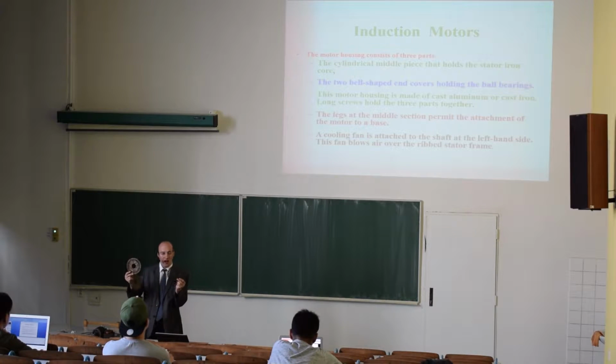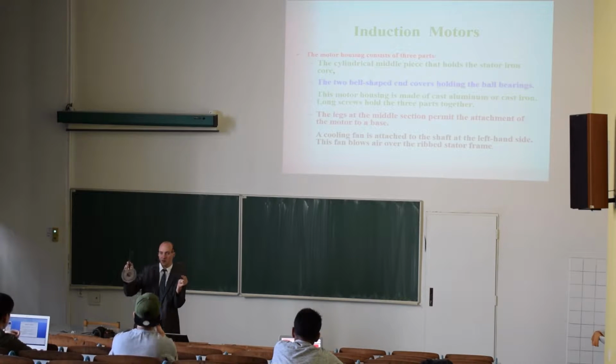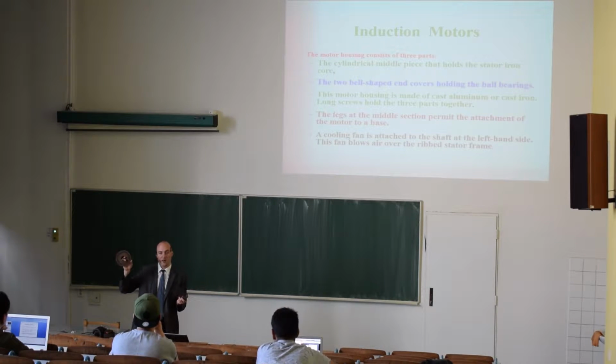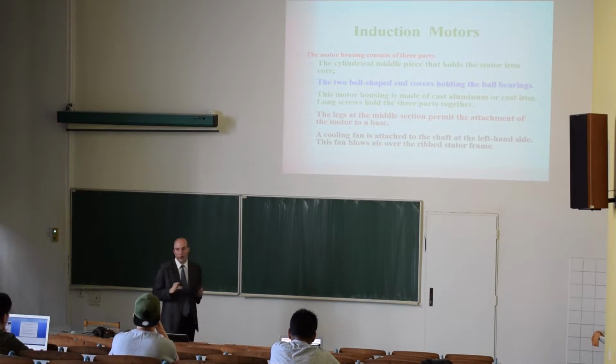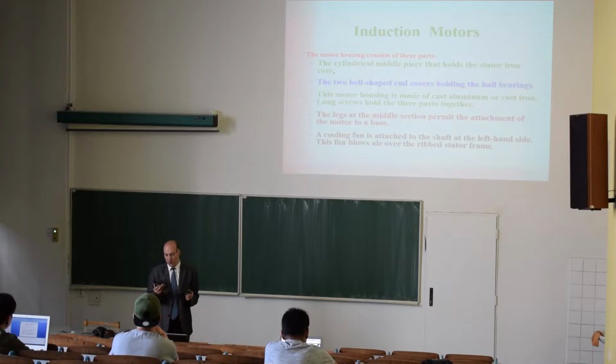So those sheets are sheets from an induction motor. So we see it's steel. It's electrical steel, so high content of silicon. We want to reduce what? Why is it laminated? Yes, losses. What kind of losses? Yes, eddy current losses will be limited by laminations. So it's not solid steel, although it would work in principle also from solid steel, but it would have high losses and therefore low efficiency.